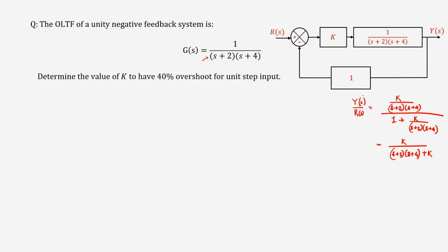So, the point here is that you see the closed loop transfer function, how many poles will it have? It will have 2 poles, right. So, since it will have 2 poles, we can directly use the formulas. Even with 3 poles we will be able to use the formulas, but then in that case we will have to keep in mind some approximation thing also. But for now we know that this is a system which will have two closed loop poles, so fine, I will directly use the formulas. So, I do not have to think much in this case.